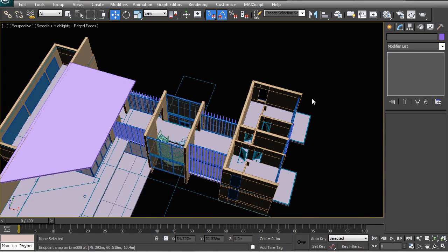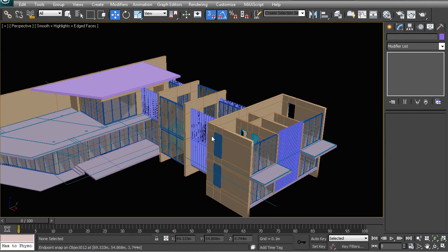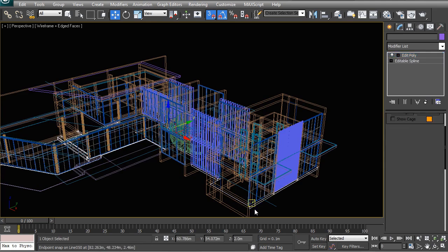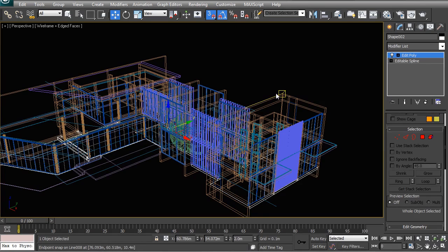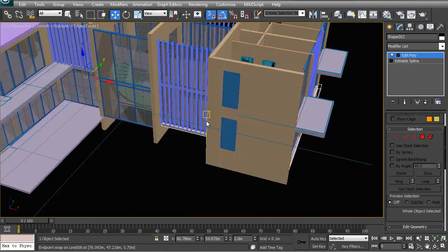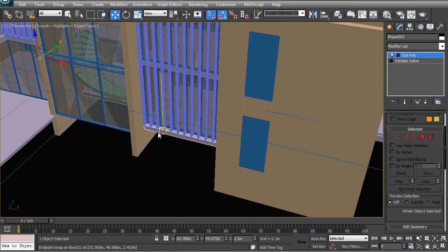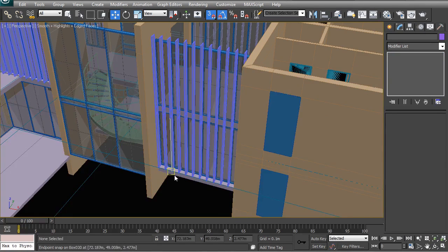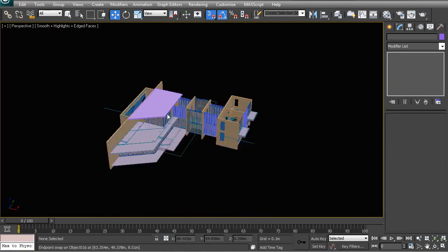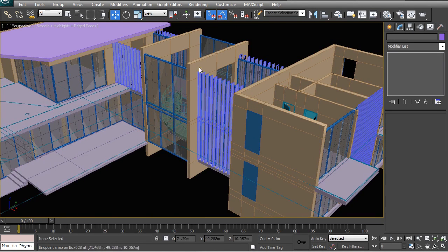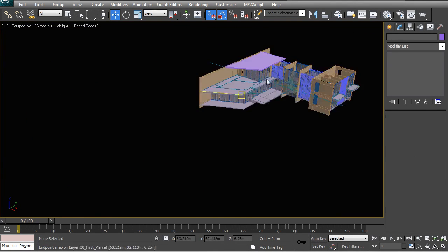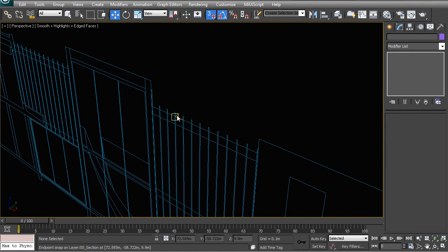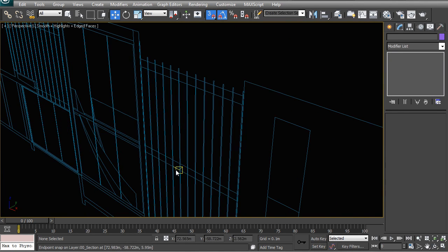We want to now model the roof for this entire area. So just like with all of the other elements on our project, you can either choose to start from scratch, or you can look whether there is an existing portion of the building that you can reuse, move, copy, and edit, and so forth. So I'm going to choose to use the ground floor, and this is because the ground floor has this extra bit of distance with a slab, and I want to have the top of the slab pretty much repeating that. If you don't want to necessarily cap these screens, in other words, if you don't want the slab to be above the screens, but you want the screens to go past the slab, then you would rather use the second floor level. So that's exactly what's happening here, is we have these screens going past the floor slabs.